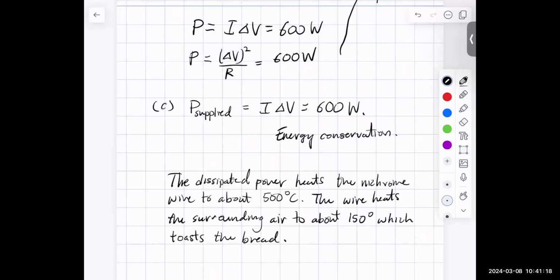If we take a charge and move it around a circuit, it'll experience a bunch of changes in voltage and some corresponding changes in its energy. But if we have a closed loop so that it finishes at the same point that it starts, then all those changes in energy have to add up to zero, or equivalently, the changes in voltage have to sum to zero. That was the Kirchhoff voltage loop rule.